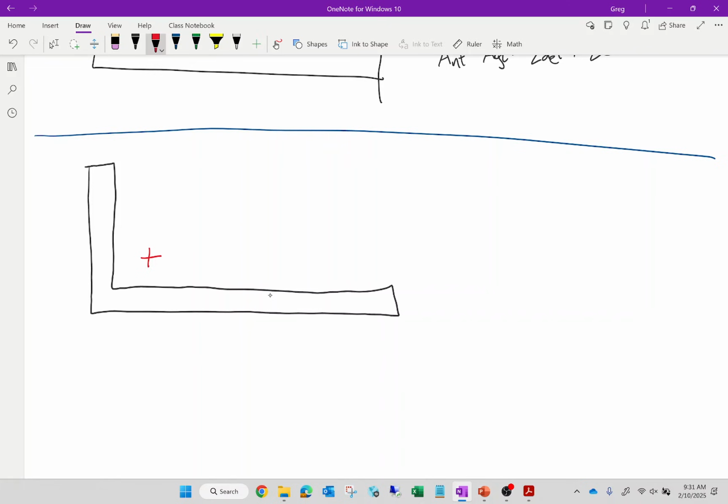If the bolts are going through this leg, then the X bar connection is this distance. In the manual, that's X bar. This dimension is Y bar. Here's what I'm saying: it's not that for an unequal leg angle you always use X bar, or always use Y bar. It's where the bolts are going through.